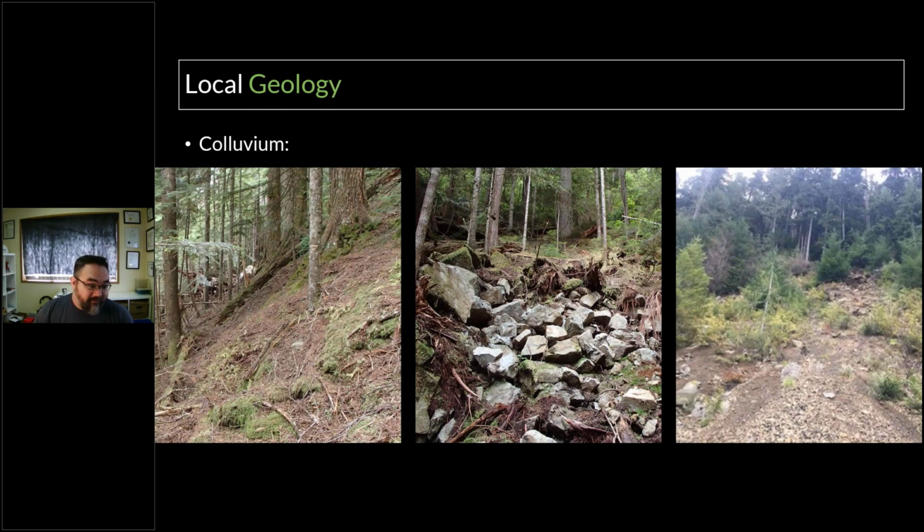In that particular type of colluvium, I know what happens there. We actually moved this road, and the picture on the right is not the same area, but it's the same type of ground. And that is a retrogressing cut slope in colluvium. So I'm standing on the road, the current top of that retrogressing cut, the headscarp, is over 60 meters above the road now. And in places, it's still over 2 meters high vertically or overhung a bit in that blocky colluvium. So you can see some of it stabilized, but that's going to continue to retrogress until either the colluvium runs out or you hit the top of the hill.